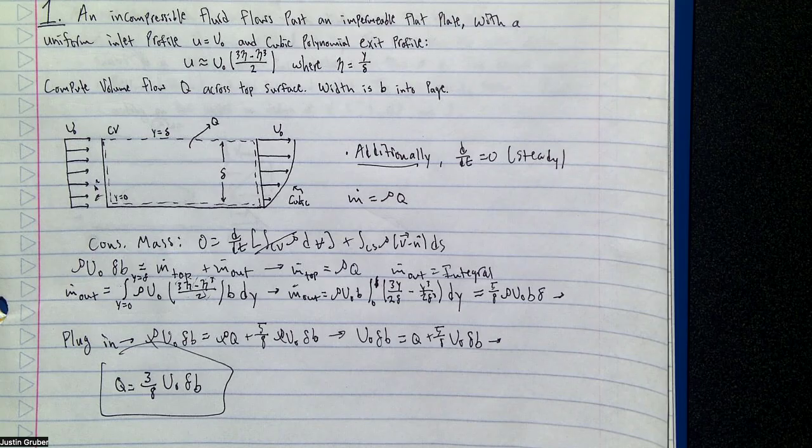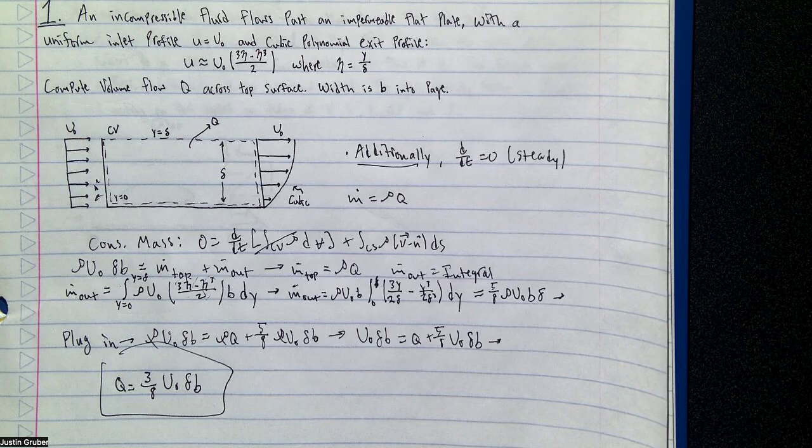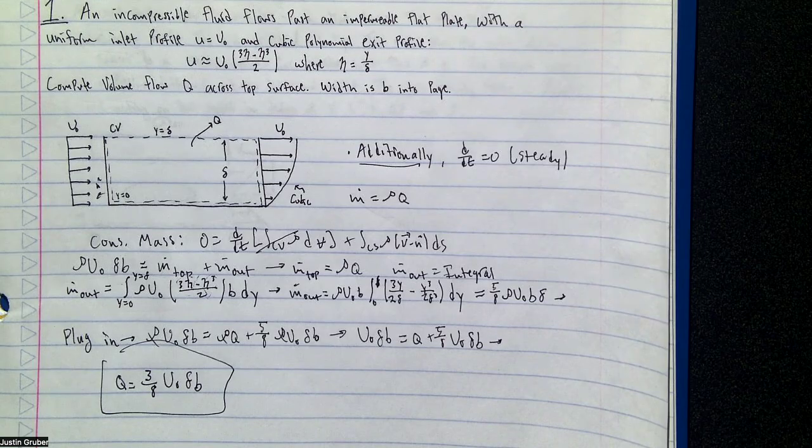Anyway, cool. All right, anything else? Nothing crazy. It's just the same stuff we've been doing, but you can't assume that every inlet and outlet is rho VA. You just have to remember it's actually an integral you're doing. And by sheer coincidence and simplicity, we can get everything down to rho VA. But really, it's nothing different. It's nothing too bad.